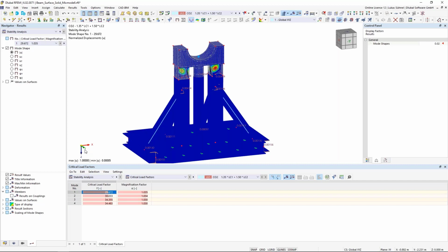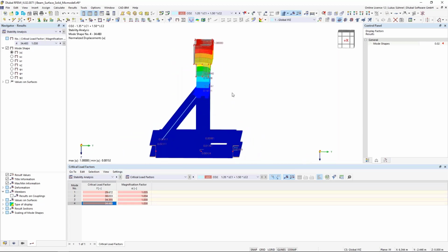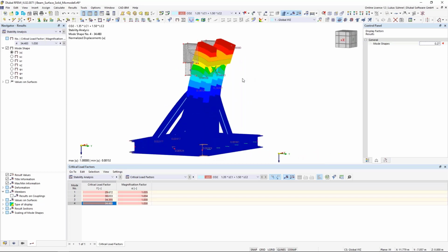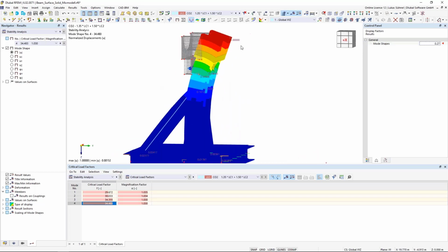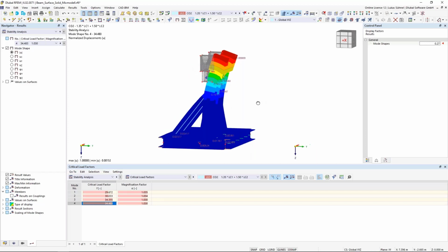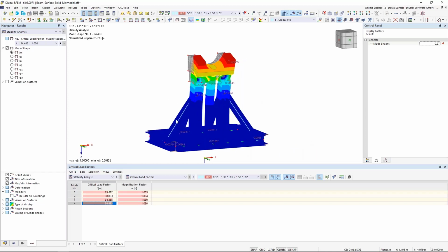And if I want to analyze it even further, I would have to look for an eigenmode that actually deals with the buckling. And this could be, for example, the force eigenvalue, eigenmode. And here we see this would be some kind of buckling for my columns. I have here the factor 34.5, so much bigger than 25. So I can easily say buckling is not an issue.